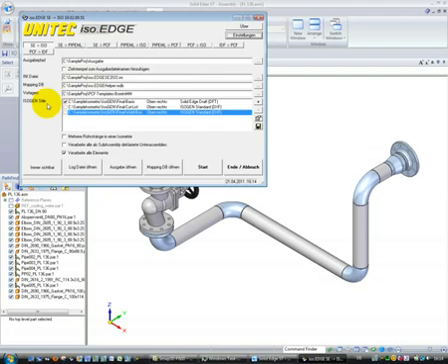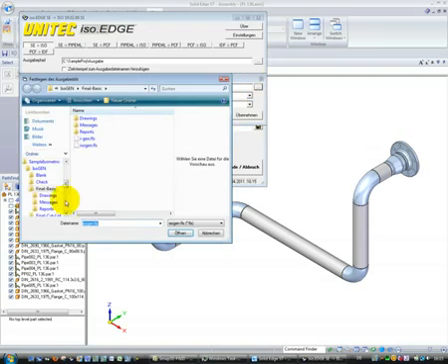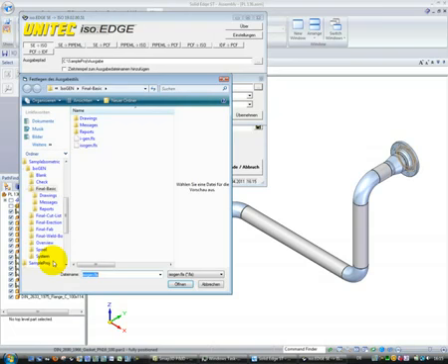With these IsoGen styles, a company can influence the display of their drawings, with the lists which should be displayed on the drawings, the drawing header and so on. These IsoGen styles are delivered with the software. About 10 prepared styles are delivered with the software itself, and a company can change these prepared styles to their own needs.